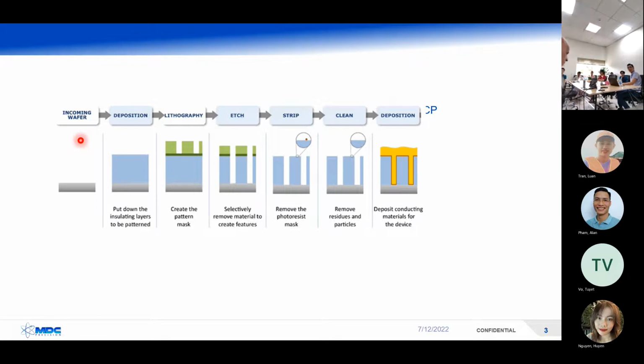So then, I mentioned earlier, this is silicon dioxide, okay? So silicon reacts with free fluorine. As these areas are exposed to this active gas, and they're excited, they have some energy from the electricity. Even though the silicon and the oxide are sitting combined together, the silicon says, hey, that fluorine is kind of cool. It's all active and dancing around, and the silicon gets pulled chemically to the fluorine. So basically 4 fluorines gather around and pull away the silicon from the oxide. So now you have what's called silicon tetrafluoride, okay? And now you have an oxygen atom floating around, right?